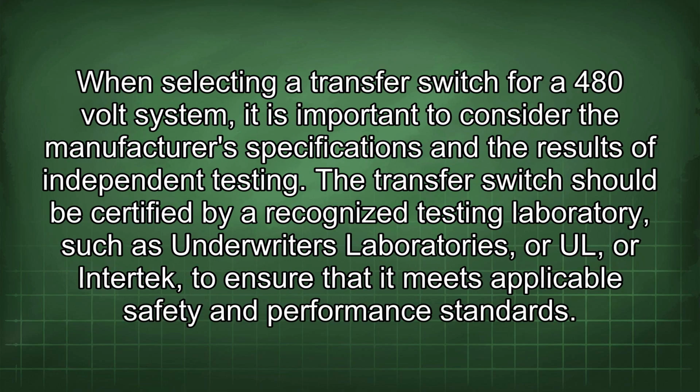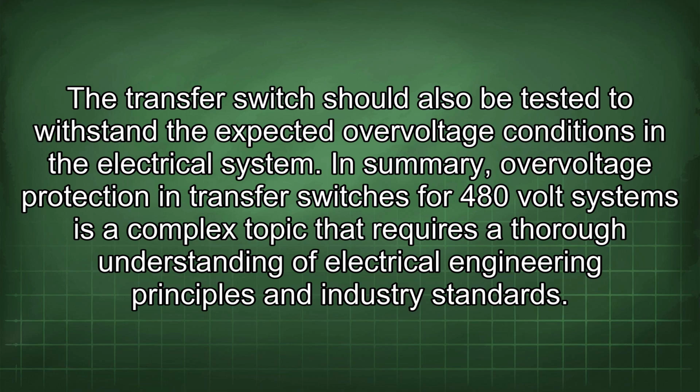When selecting a transfer switch for a 480-volt system, it is important to consider the manufacturer's specifications and the results of independent testing. The transfer switch should be certified by a recognized testing laboratory, such as Underwriters Laboratories, or UL, or Intertek, to ensure that it meets applicable safety and performance standards. The transfer switch should also be tested to withstand the expected overvoltage conditions in the electrical system.